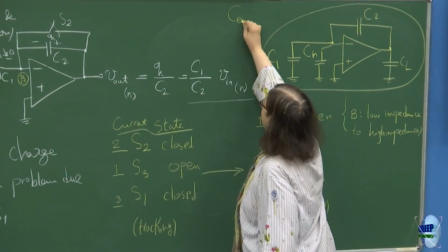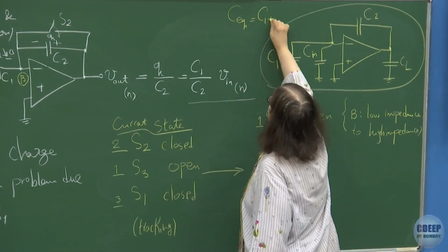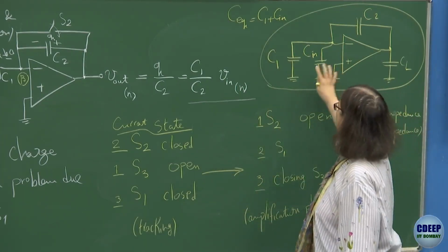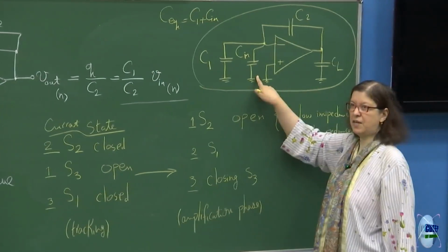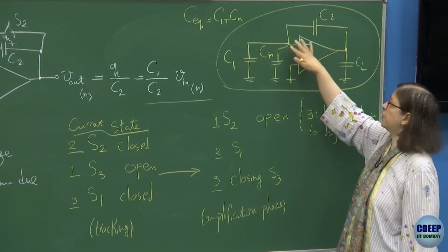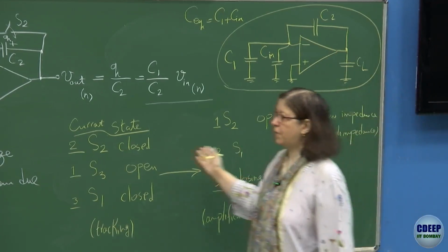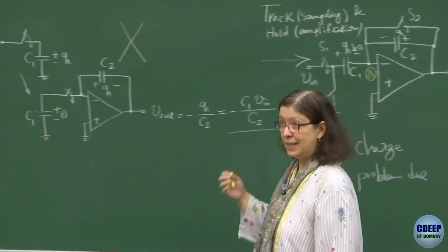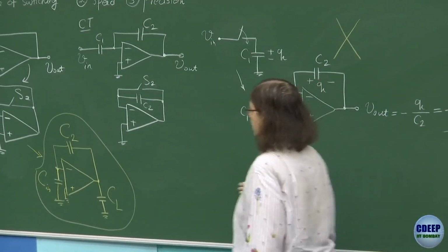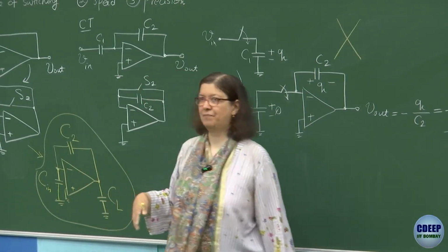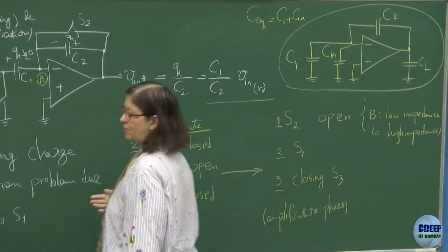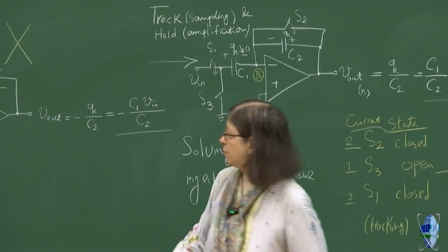say, C equivalent equal to C1 plus Cin, the two are same. One op-amp, one capacitance from negative terminal to ground, one capacitance at the output, again between output and ground, and one feedback capacitor. So therefore, both of them show same speed, parametric wise. But value wise they are different, because now instead of Cin, we have Cin plus C1. So we just replace what we had before by adding the C1 to Cin. So therefore, we don't need to do the recalculation.